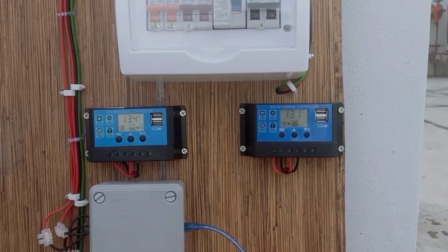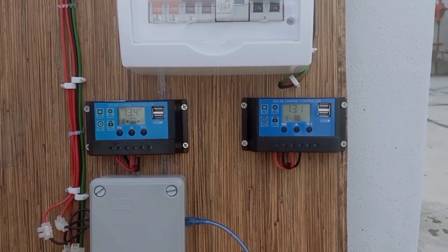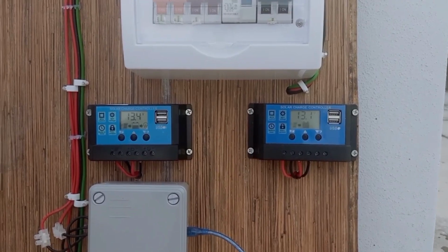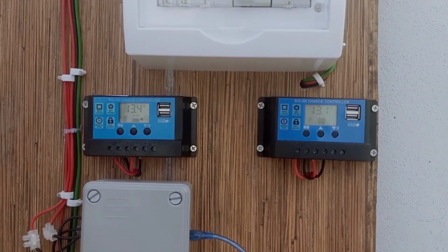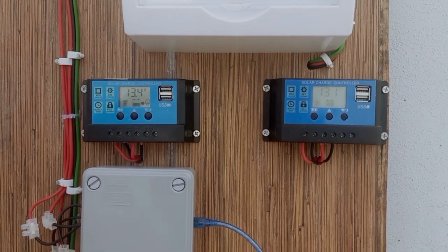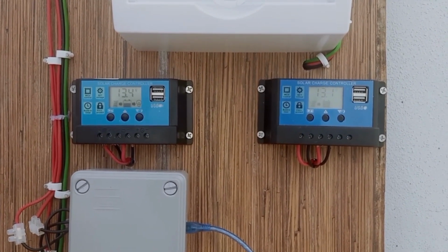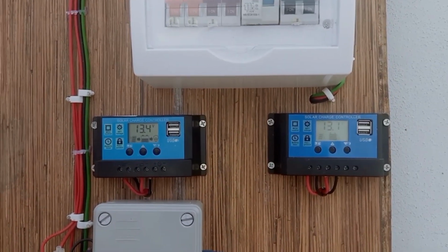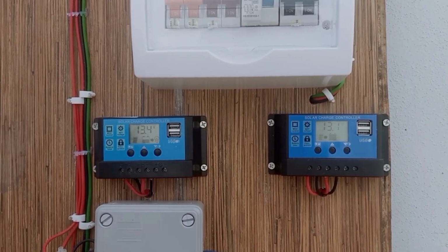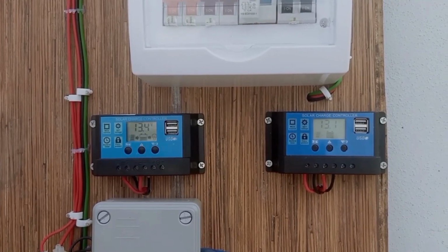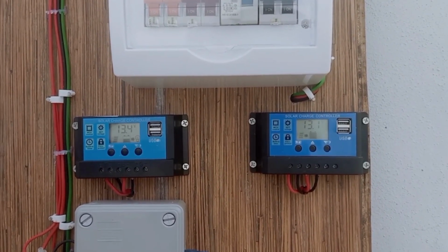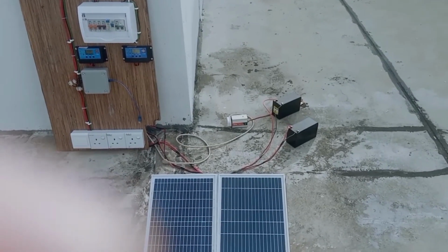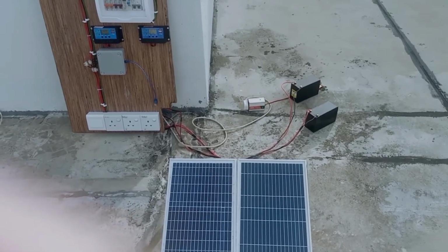Okay, for the energy we produce, we use solar panels of 10 watt, and we use 2 solar panels, so the total is 20 watt. And then the energy produced per day is 20 watt multiplied by 4, and we can get 80 watt. Why do we multiply by 4? Because the average sunlight in Malaysia is about 4 hours, and with 80 watt we can charge 12 handphones or 2 laptops.